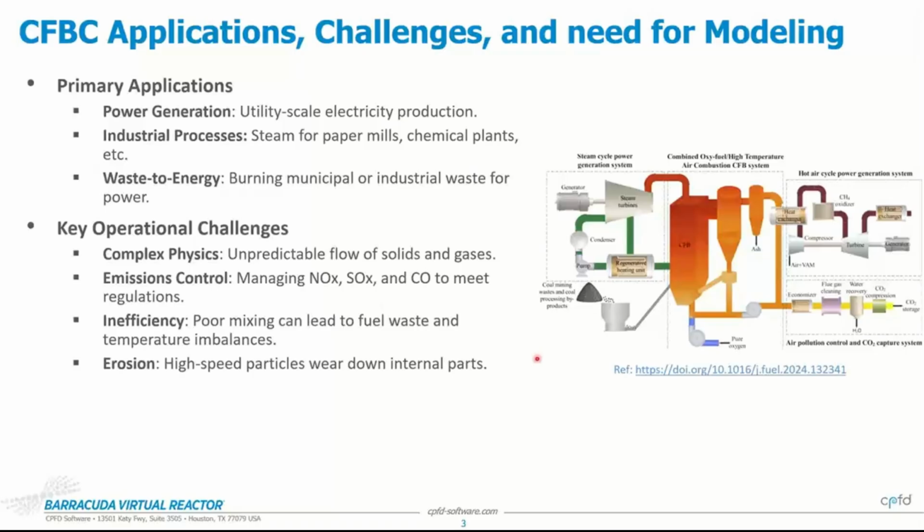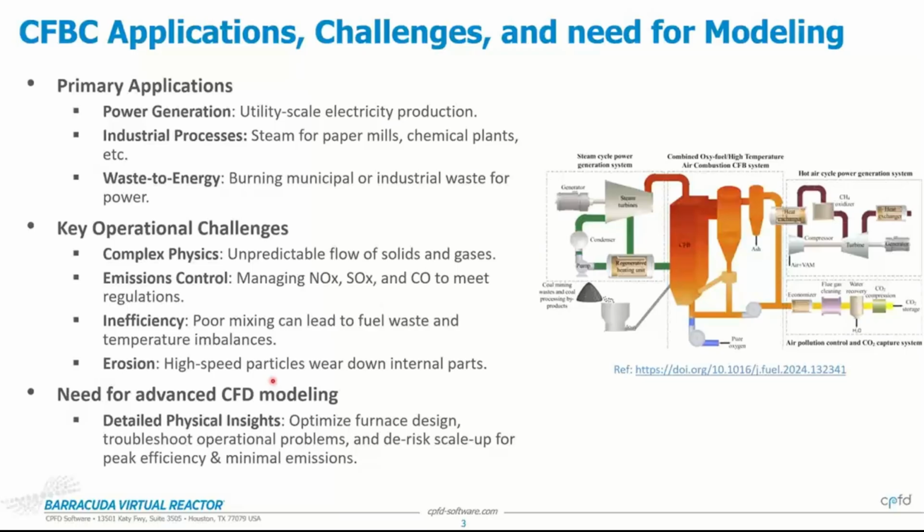Essentially, if the fluidization operation is not happening properly, then that leads to inefficient mixing, so your combustion is not taking place properly, and it can also lead to hotspots. And anytime there is high velocity gas with particles, you always run into the issue of erosion, essentially. So that's also something to deal with. And this is where CFD modeling can actually help out.